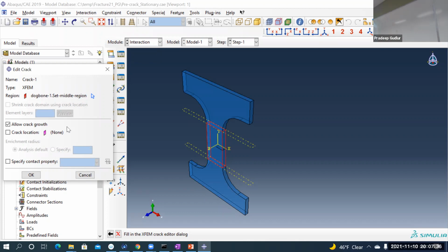At that location, in this volume, all the real nodes will have phantom nodes also. We'll see that appearing in green in a second. So that's the domain that I picked. That's the advantage of the extended finite element method: it creates phantom nodes for us.